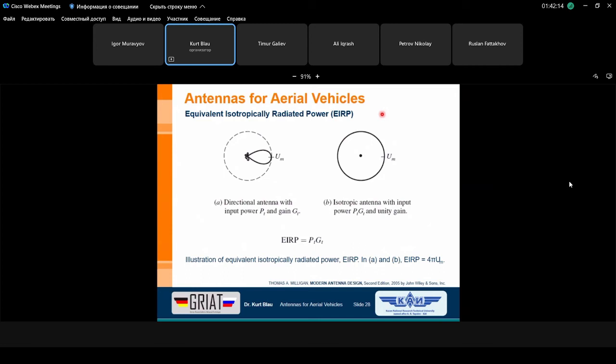Then I have to connect it with an antenna, and the antenna has a gain of, let's say, 6 dBi, meaning the antenna has a gain in linear scale of four times the gain related to an isotropic radiator, meaning a radiator which has a pattern like a sphere.